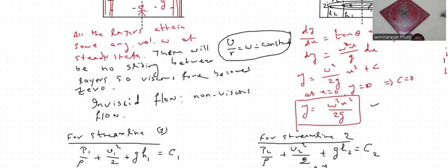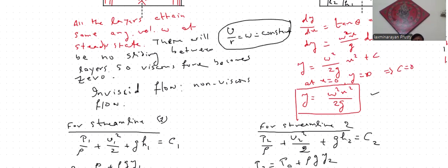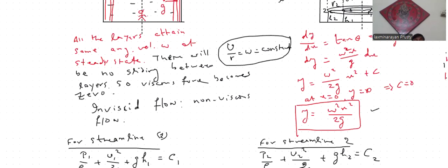This point, that the total energy per unit mass is constant along a streamline, is what is given by Bernoulli's theorem. But Bernoulli's theorem never compares the total energy per unit mass between streamlines, because using Bernoulli's theorem we cannot arrive at that result.